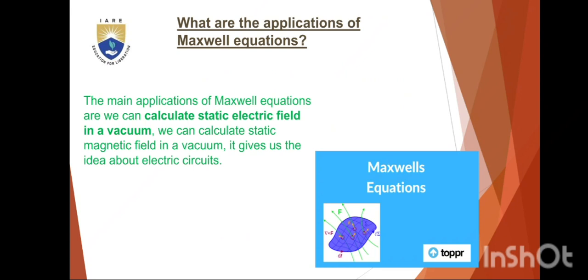Here the scalar magnetic flux can be replaced by φ is equal to integral B bar dot dS bar. It is equation 3. Substitute equation 3 into alternating EMF is equal to minus d by dt integral B bar dot dS bar, which is a partial differential equation.